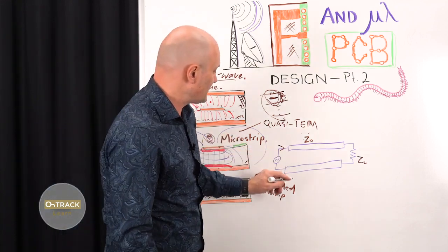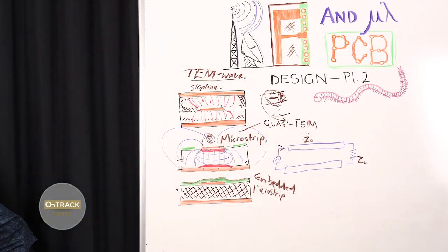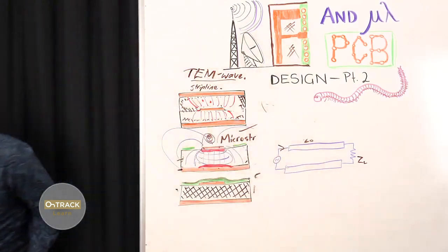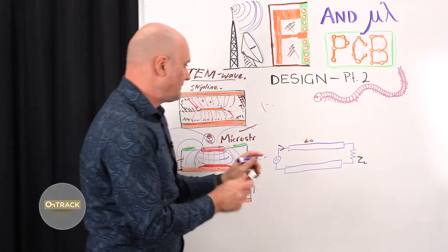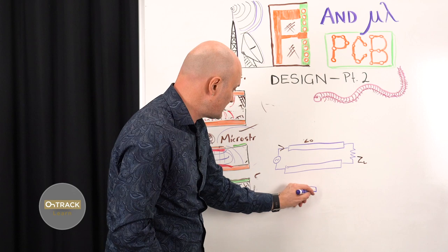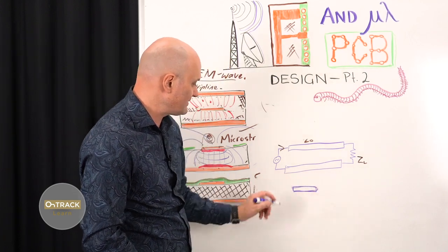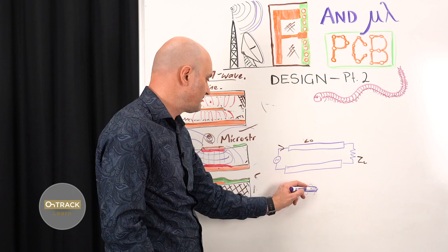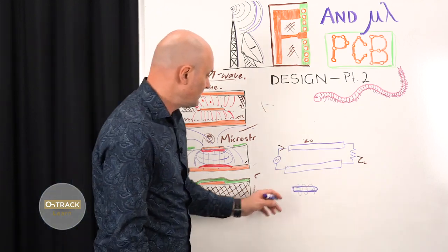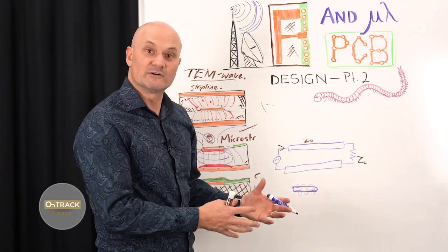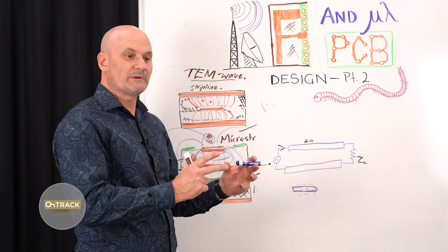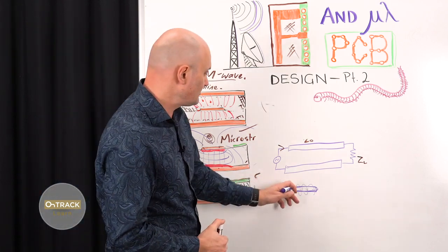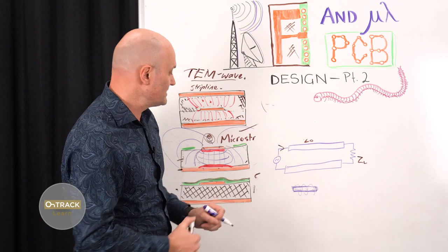And the impedance is typically characterized, so a transmission line, I'm going to have to erase more here to make room, so please forgive me. Okay, so the way of looking at this is there's conductors, and a conductor, a piece of copper like this, which could be a section of trace, has inductance. So when current's flowing in a particular direction, a magnetic field is set up around the trace. When it flows in the other direction, the field reverses. Energy is stored in that field, and it takes time to set up, collapse, and reverse those fields, right? So there's some delay to this, and that delay depends on the dielectric, and it depends on the characteristics of the metal conductor and other materials around it.